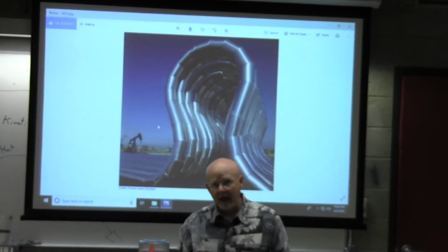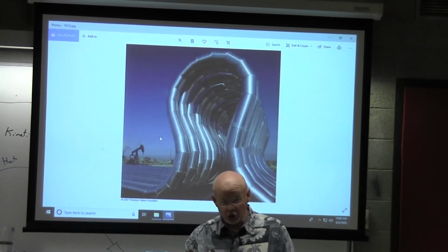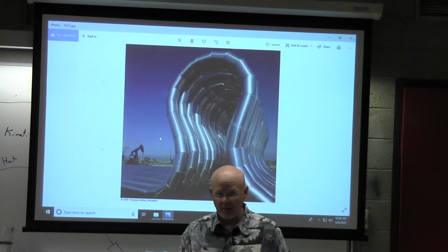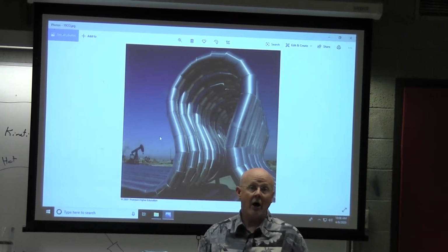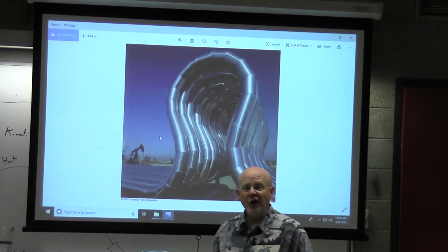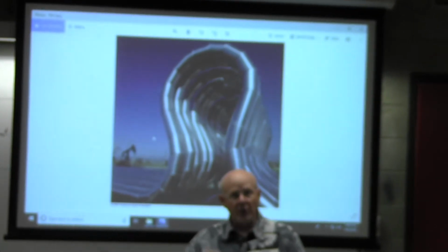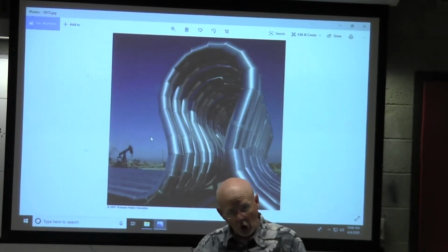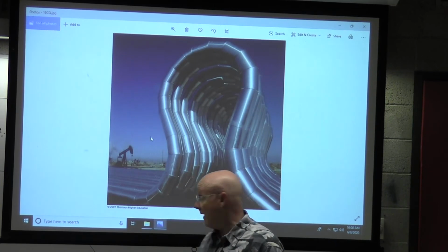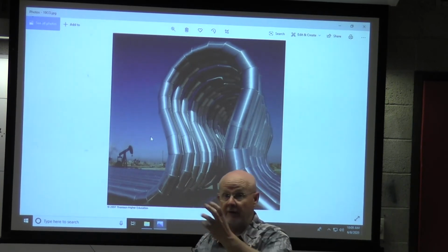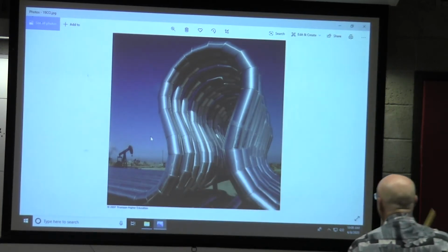And so if you build a metal structure that is super, super long, like a pipeline, 900 miles, or a railroad track, which may be hundreds of miles, then even though it doesn't grow much per 1 meter, the total growth could be a lot, and you need room for that. And that's why those railroad tracks kind of curved. They needed that extra space, and that's what these are for.